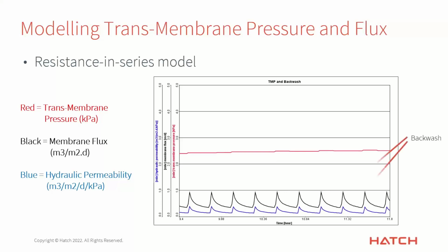So the backwashing events, you can actually see them if you run at a small enough communication interval and a small enough window that you could see these things happening. So this entire simulation here is actually just a few hours. We can see every 15 minutes there's a spike. And this is the backwash event happening, blowing all of the solids off of the membrane.